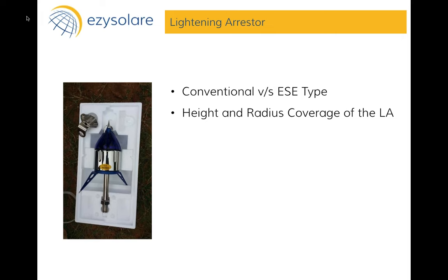The reason for that is that in rooftops, the run of the cable, run of the earthing strip, or the length of the earthing strip is not very high, and as a result, the rule of the total resistance in the earthing strip being less than 1 ohm can be easily followed even with the 25 into 3 earthing strip. This was about the earthing strip.